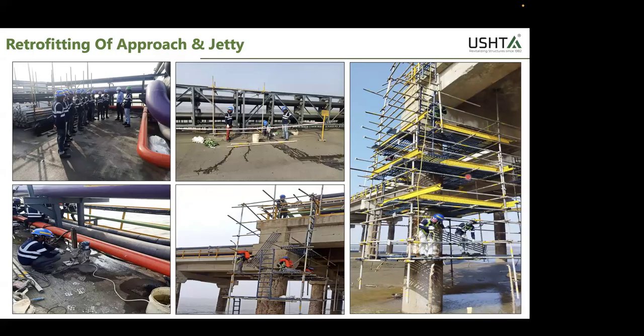So you have to be very careful in designing right from your scaffolding, because scaffolding is hung. It's not from the bottom to top, it's hung top to bottom. And you design in such a way that it can take care of the tidal wave. So now you can see this is dry. This is near the approach. And suddenly you'll see water up to the beam bottom. So the tidal variation should be considered, wave velocity should be considered. And again, the live load of people working, that also has to be considered.